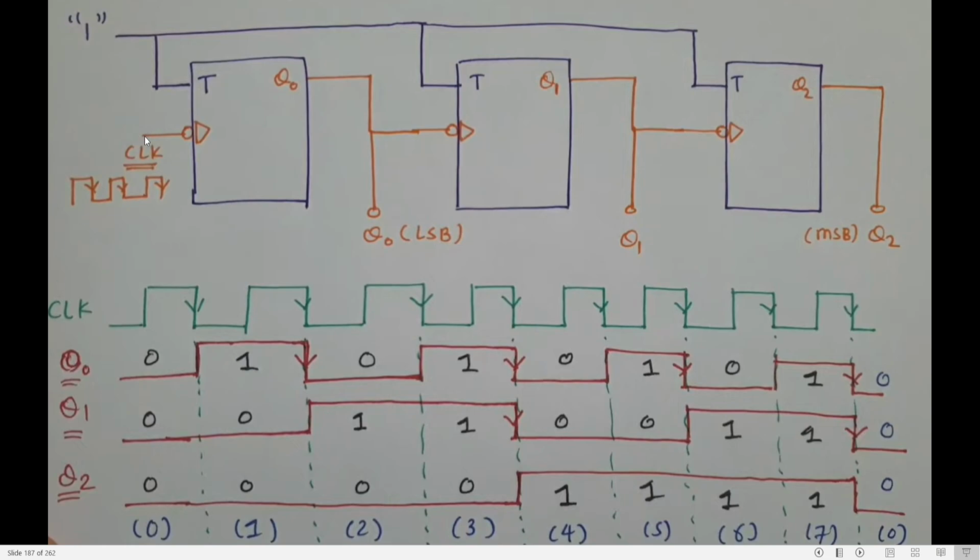You should know that the T flip-flop will work only in the negative edges. So in the clock, in all the negative edges, draw the arrow mark showing that the flip-flop will work only in the negative edge. First draw the arrow mark in all the negative edges. What is negative edge? If an edge falls from 1 to 0, it is a negative edge. Done. Now how can I get Q naught? First, draw Q naught.